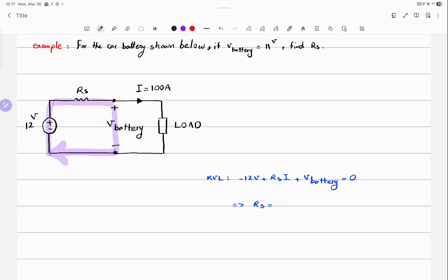I don't know what that is. I think it's very small. It's 10 milliohms. It's small, right? Why can't I just neglect it? A large current is being drawn from the circuit. That makes the voltage drop across that 1 volt. 1 volt is not negligible, okay?